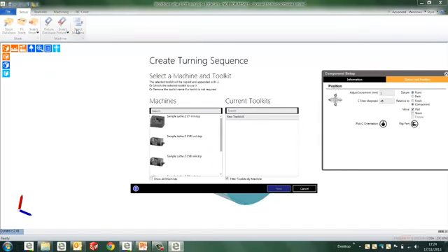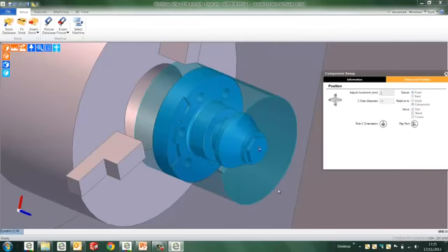Now we can load the part into the machine tool. Here I'm going to pick a sample machine tool from the installation of Edgecam. This is the place where we'd implement the custom post-processors. Once we select the post-processor, we're then offered a series of toolkits. This could be a representation of the job that's been pre-kitted, or indeed standard tools within the machine tool carousel. So once we've picked the kit, we can now move on to the next stage, which is the Features tab.